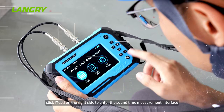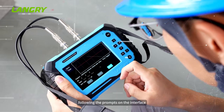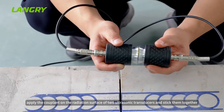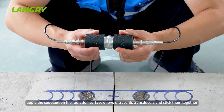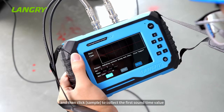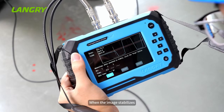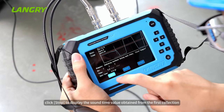Click zero setting on the right side to enter the sound time measurement interface, following the prompts on the interface. Apply the couplant on the radiation surface of two ultrasonic transducers, and stick them together. Remove any air gaps, and then click Sample to collect the first sound time value. When the image stabilizes, click Stop to display the sound time value obtained from the first collection.